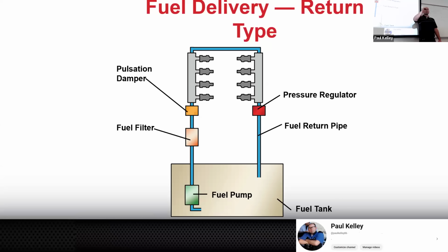It's adding fuel that it wasn't planning to add because you have a tear in the diaphragm, right? So remember, in the next lesson, when we start talking about air-fuel ratio, that's going to mess up your air-fuel ratio. You want 14.7 to 1, and instead you thought you were getting 1 pound of fuel, but little did you know, we were sucking another pound through the torn diaphragm and the pressure regulator. You're like, why are my numbers off, right?